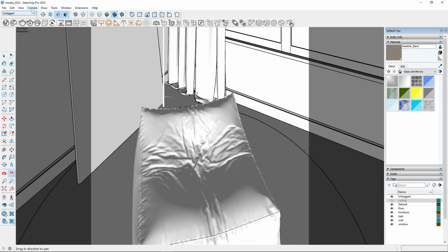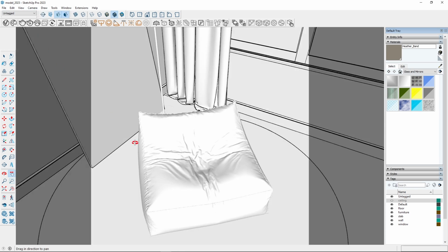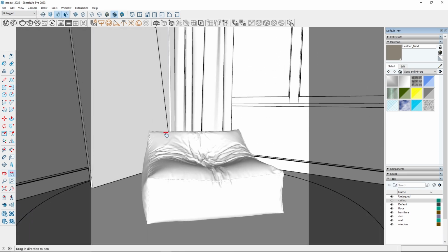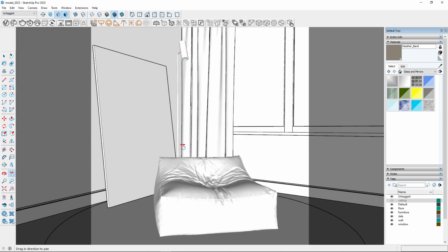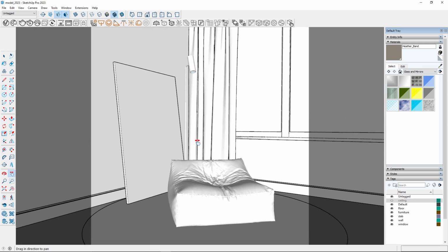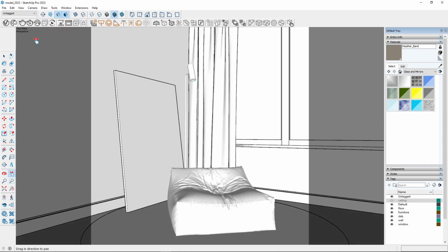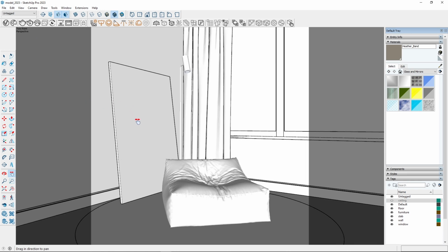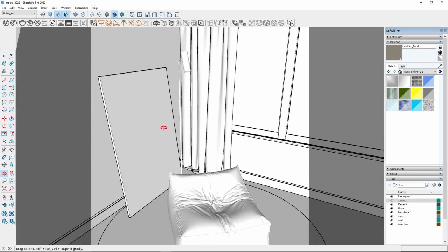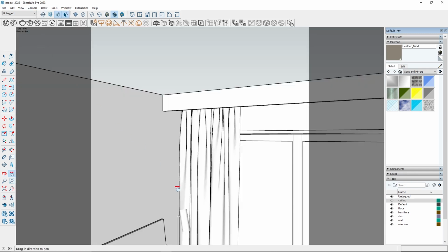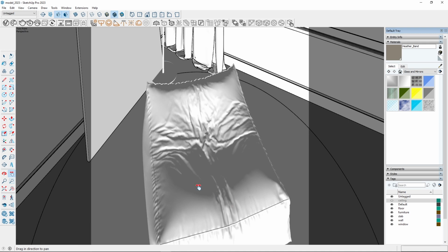So remember to firstly go to perspective view, try to find the best scene, for example, something like this. And in this scene, my view is almost 2-point perspective. And then you can adjust it to 2-point perspective and everything works fine. So this is my advice. Not to start with something like this when there are no vertical lines, because then you can have a weird scene.